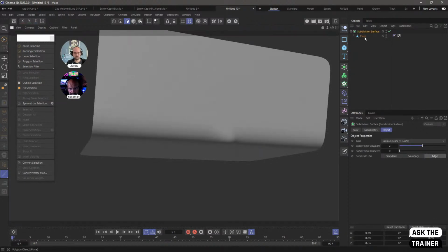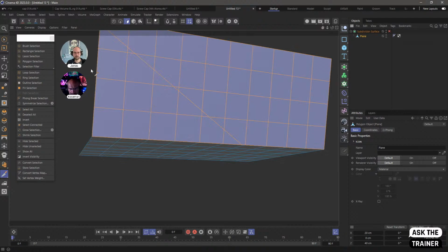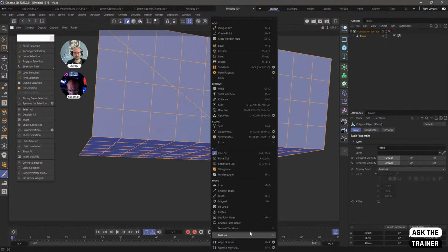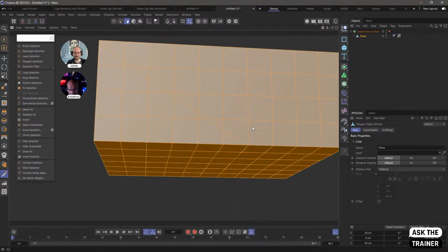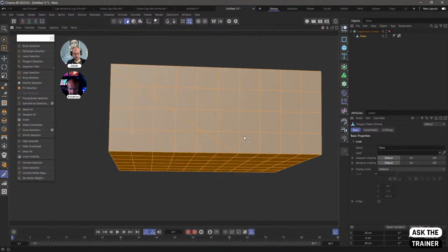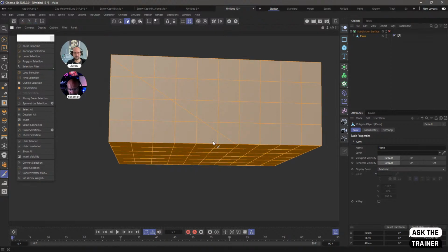So in this particular case, if for whatever reason, let me just revert the normals because this just freaks me out. So if I really, really wanted these polygons to have this cut here, the solution is pretty simple. I'll make sure that that ends before the curvature starts. So in this particular case, I can split the model.